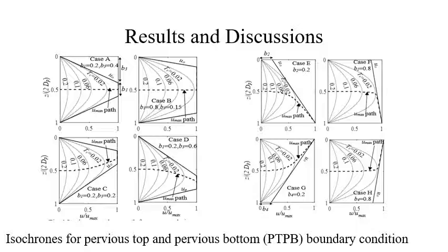The impact of trapezoidal initial excess pore water pressure on the progress of the consolidation phenomena is presented by a series of isochrones and consolidation curves. Here we take eight different symmetric and asymmetric shapes of pore water pressure for the analysis. Due to variation of initial excess pore water pressure, the isochrones are presented in normalized form.